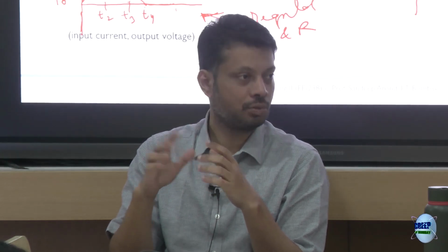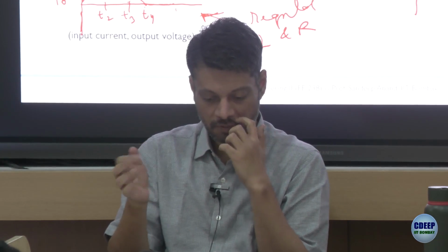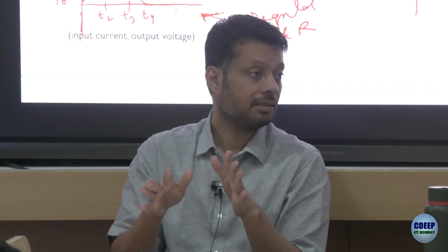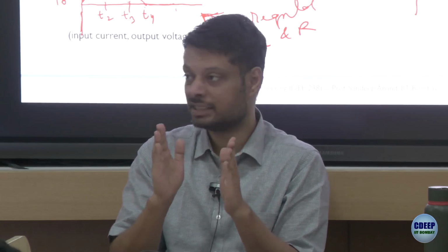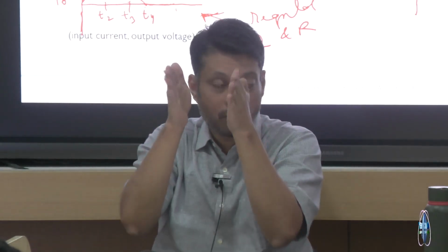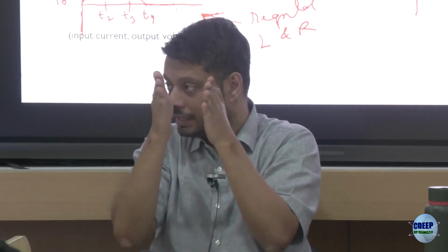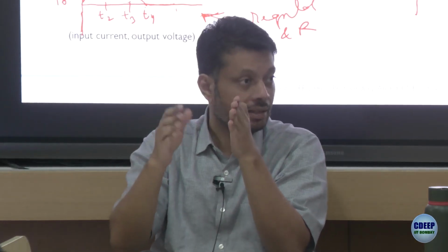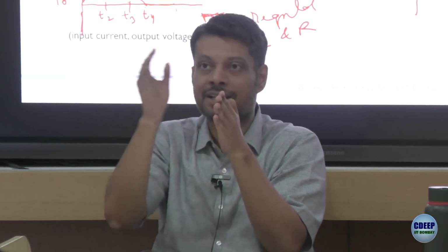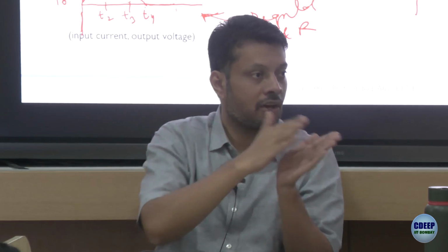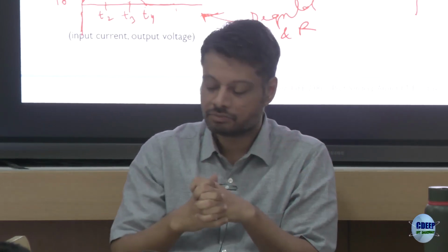Yeah. So two things, I think maybe both of you are trying to say the same thing. One is that it's a non-linear circuit. There's a diode, it's not a linear circuit. Now what you are saying is, okay, forget about the whole period, I'll only look at this small period. It's a linear circuit, yes, but in this small period you don't have sinusoidal steady state. You are not able to complete a cycle. It's half of a cycle, right? So you cannot use the same explanation here.